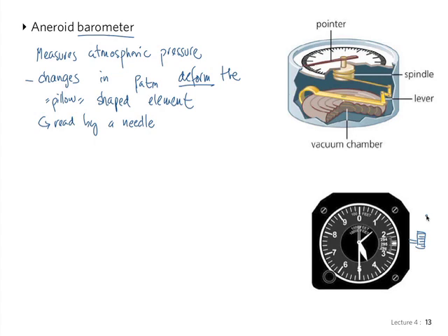If it was 29.92 inches, we know that's standard atmosphere, 29.92 inches of mercury. But if today we have good weather and higher pressure, he will say, set your altimeter to 30.1.